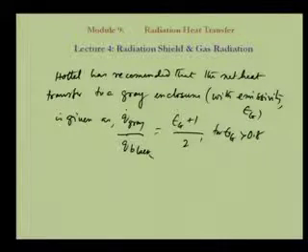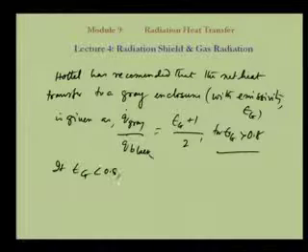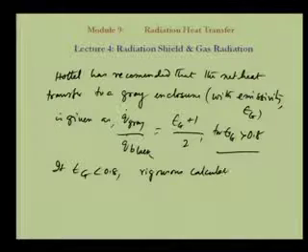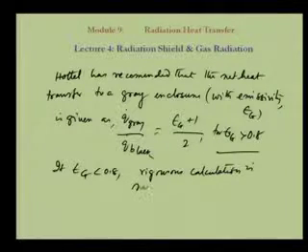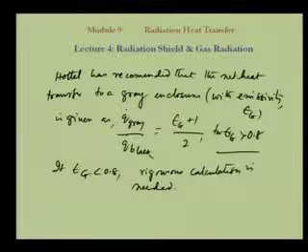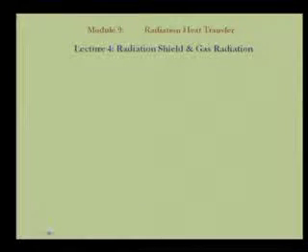That means, for higher values for gray, we have seen that for the black enclosure. Now, if we have a gray enclosure, then we can calculate from the black enclosure, provided that epsilon g is greater than 0.8. If epsilon g is less than 0.8, then rigorous calculation is needed, which is beyond our discussions in this particular lecture hours.